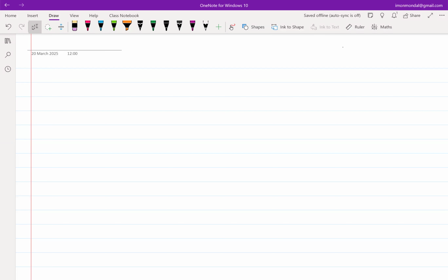oscillations, because no device is unilateral. There is always some unintended feedback from the output to input, because of maybe some parasitic capacitance or some parasitic route. Because of that, you can have an exaggerated version of the output getting fed back to the input, depending upon how much swing you have. Hence, characterizing a device based on the traditional Z parameters and Y parameters was not feasible.